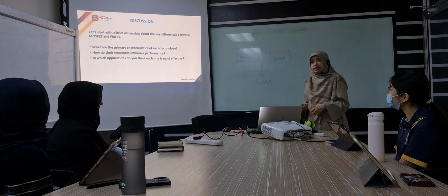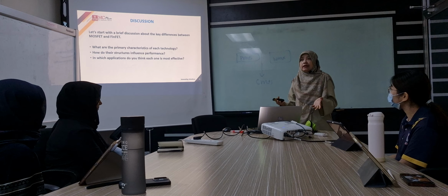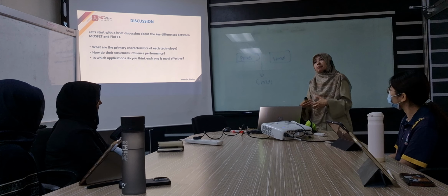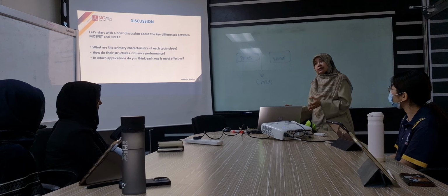I remember FinFET used the technology below 220, and yes, because it can work in smaller channel length. That's why it is called a rescue to MOSFET limitation. But if you are planning to design something like an amplifier or analog circuits, normally we start with MOSFET. Okay, FinFET is good, but more design on digital.